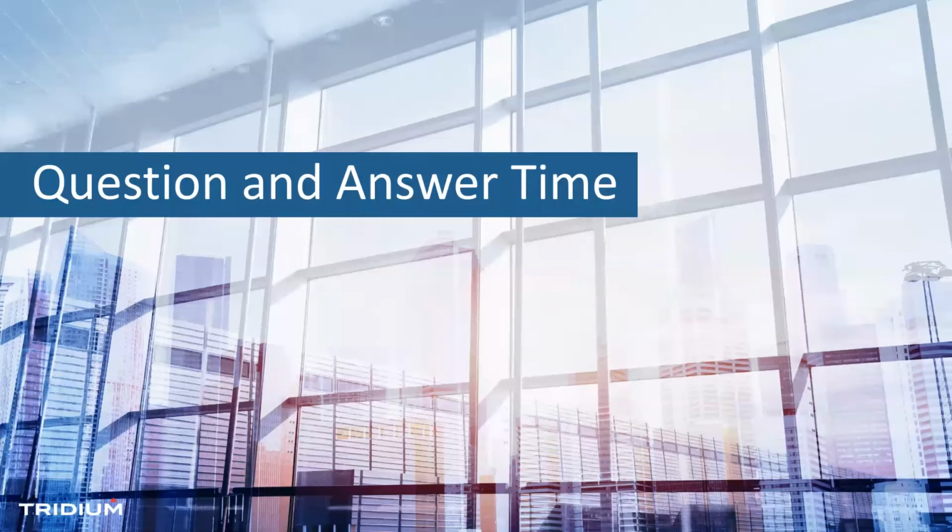Anybody else? Oh, here we go. The next question that came up is: do we have specifications or guidelines for allowing the exportation of building system data to an external data warehouse? Well, that's a great point. We didn't get into details of it today, but there are new protocols. You don't use BACnet to export data to the cloud for the most part. You use things like AMQP or MQTT. And I think that's why, on that integration matrix, that's where you would do that.